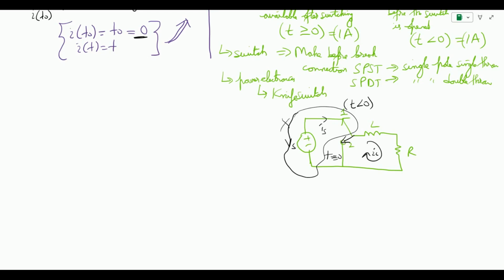If we consider the initial condition when time was less than 0, we know that a constant current was getting applied. Let's say the voltage was 10 volts, then how much current is going to appear if the resistor is, let's say, 10 ohm. We know that when a constant voltage supply was given, the inductor was acting as a short circuit. So I can remove this and have a short circuit over here. For a long time, the current comes out to be V by R, which is 1 amp.